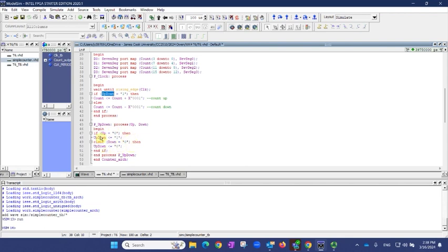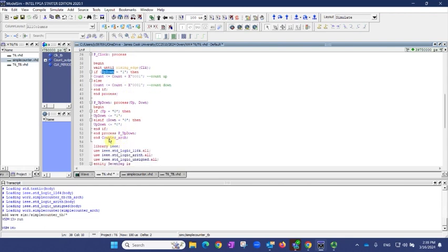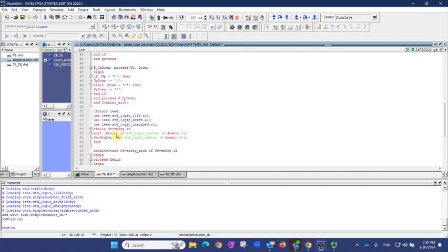You can define that, but if I design the circuit, I will only have one switch, right? If the switch equals 1, then it counts up. If the switch equals 0, then it counts down. Because if you have 2 switches, you actually have 4 combinations, and we only use 2 possibilities there. So there are 2 combinations not being used. But anyway, you can do that, and this definitely works. And you end all those processes and the entity, and you end your architecture. So the following is that one.